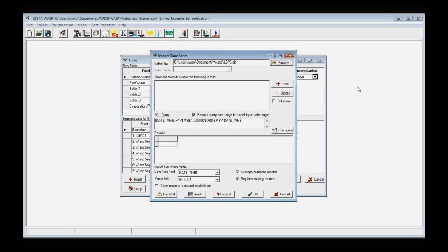In our case, it only contains one because we queried it out, but if it contained more than one subbasin, we would have to do a query on station and find the station that we want. And then we also have to do the same thing for the parameter code because we have more than one parameter in here, because recall we have BOD, DO, flow, temperature, TN, and TP. So we're going to want to have the flow in here.